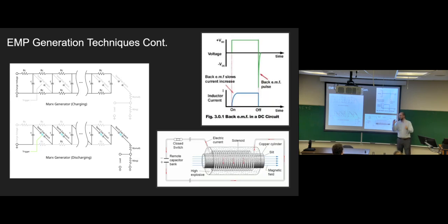What's the diameter of the loop? Well, this is why it's important that it's high velocity explosives. You're compressing this system so quickly that the physics start to break down and behave a little weird, to where the inductor had this massive amount of energy, and then from its perspective, it's almost like you swapped it out for a smaller inductor, which under normal circumstances would have never reached those peak energies. And when you compress it, out this axis you can see this magnetic field, it sends a ridiculous magnetic pulse in that direction, normal to the loop area. So it just shoots it out that way.